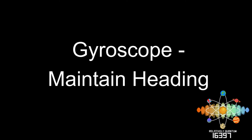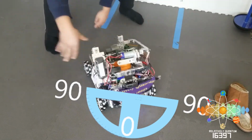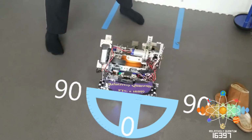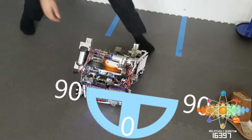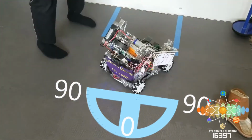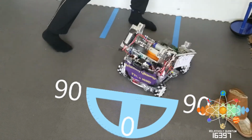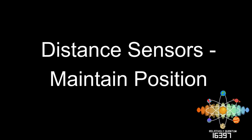Now that we're able to know what quadrant to go to, we need a reliable way of getting there. Always maintaining a reliable heading was very important for us this year, since we noticed that even a slight deviation in angle would cause rings to shoot and completely miss the narrow opening of the high goal. To ensure that we would have precise turning, we used not one, but 2 gyroscopes, one from each hub, and used the average angle of the 2 readings to calculate our heading as accurately as possible. From there, we used a custom loop that slowly accelerates and decelerates the robot to arrive at the desired angle.